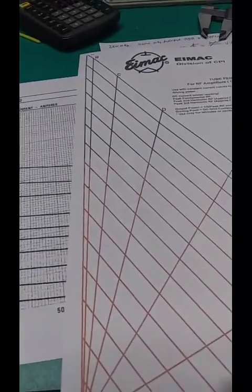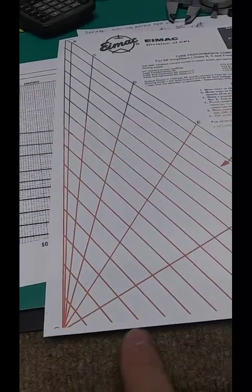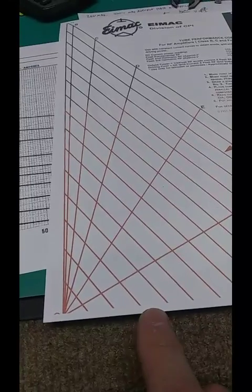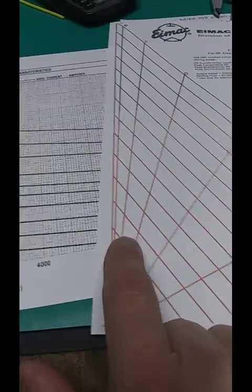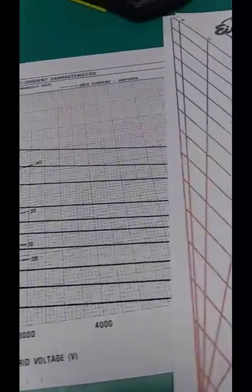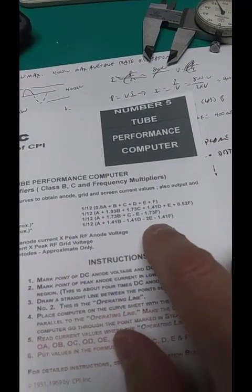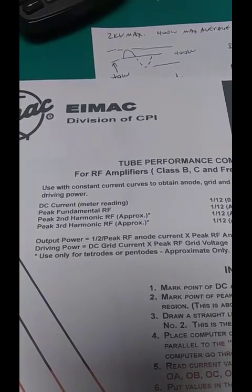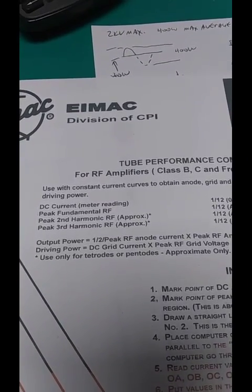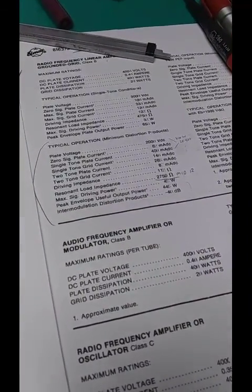And when that line length is made coincident with this line and the line down here implied where the printer cut it off, say it's the length of this diagonal line, when that diagonal line is put parallel and right on top of that line, then these radial lines indicate current levels. They're then put into these very simple formulas to calculate DC current meter reading, peak fundamental RF energy, peak second harmonic, peak third harmonic, output power, and driving power. And the proof in the pudding is that those jive with those numbers.